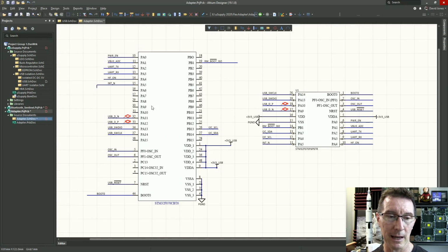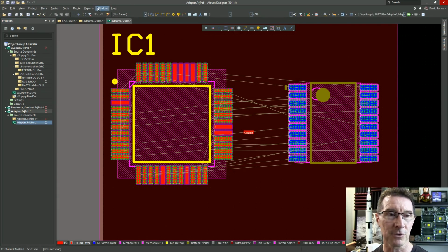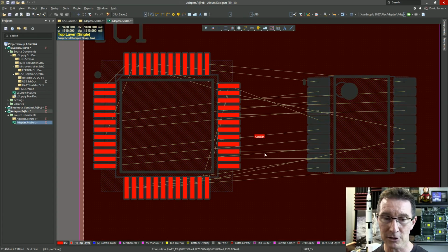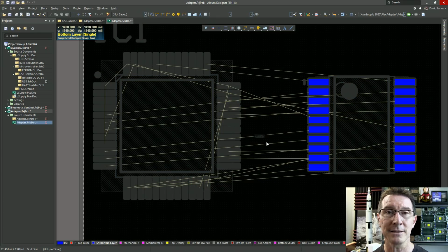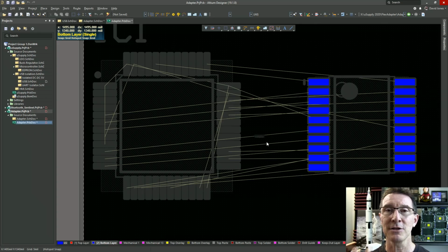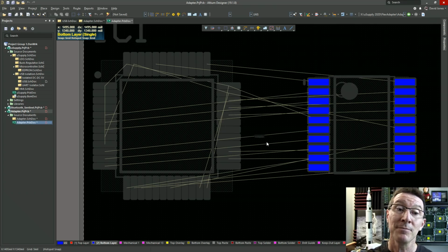Sorry. Anyway, we've got a PLCC chip, and we want to convert that to an STM32-like package over here. So we've got the adapter PCB. Now, here's where you can come a gutser real easy. This is our chip, obviously the red, on the top layer there, and then we've got a bottom layer down here. So we've only got a 2-layer PCB. Like I said, we wouldn't design this any differently to a regular PCB. It's going to be exactly the same as you would lay out, except when you go to the checkout of the manufacturer's website, you'll choose Flex PCB instead.